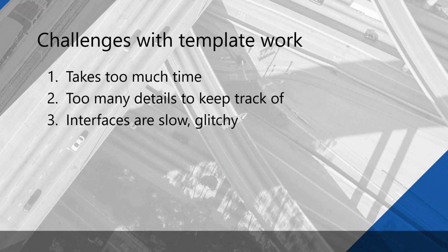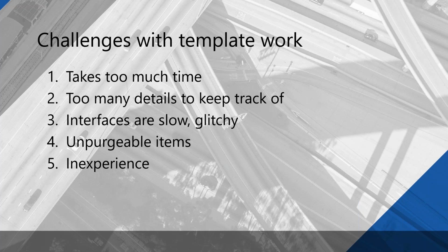There's real challenges there. A lot of the interfaces that we work in, some parts of Civil 3D for the end users can be great and pretty streamlined to work through, but the back end of Civil 3D can be pretty slow or even glitchy in some cases. As we're trying to keep our templates clean, we often run into all these unpurgeable items, be it layers or blocks or text styles or you name it, right? And we end up with this extraneous information in our templates.